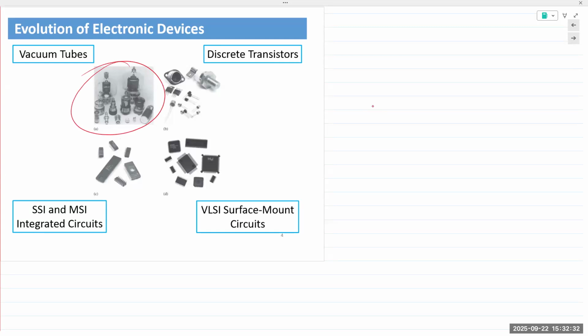And we'll talk about it when we get to the semiconductor diodes, right? So these vacuum tubes were devised as a means of controlling the flow of current between 2 terminals in a circuit. The simplest of vacuum tubes had 2 electrodes, one anode, one cathode. And when you applied a potential difference between the anode and cathode, you could actually control the flow of current, the flow of ions between the two, right? And so that's when they discovered that you could actually manipulate the flow using multiple electrodes.